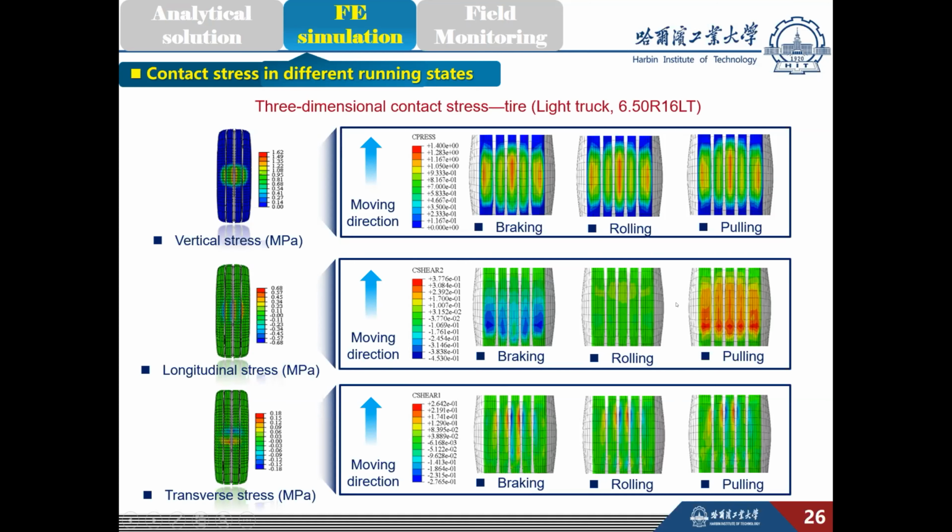This slide is used to illustrate the effect of horizontal stress loading on dynamic response of pavement. Three cases were compared here: three-directional loading in the light blue line, horizontal loading in the red line, and vertical loading in the purple line in each figure. The observing point was selected at the top surface layer, right under the tire center line.